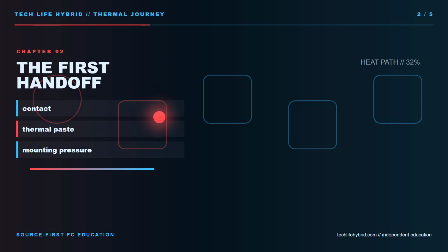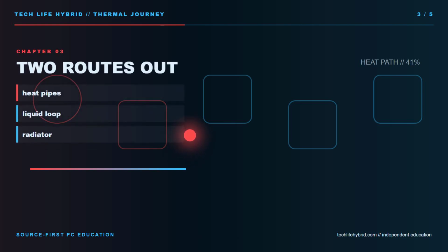Each route has practical trade-offs. A large tower cooler needs socket support, memory clearance, case height, and a sensible airflow path. A liquid cooler adds radiator clearance, tubing position, a pump, and more possible failure points. Pump orientation and radiator placement matter, as do maintenance and the exact manufacturer instructions. Choose a system you can install, inspect, and live with, not the one that simply looks most dramatic.